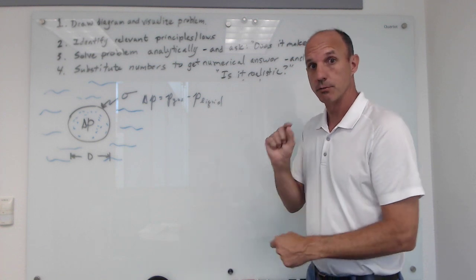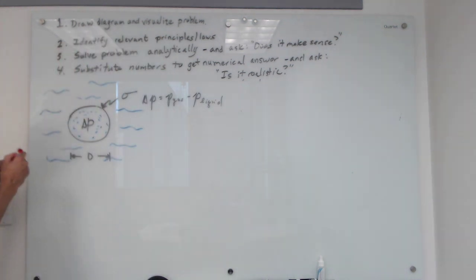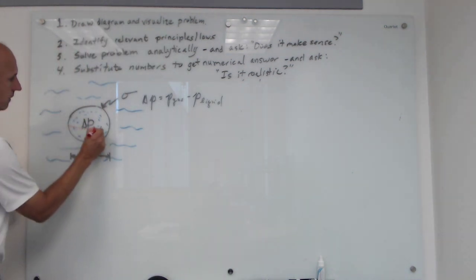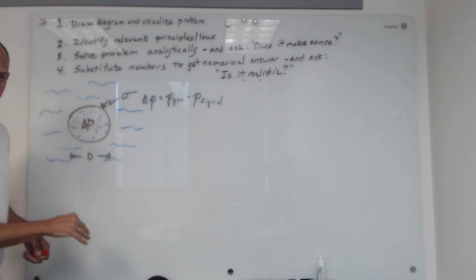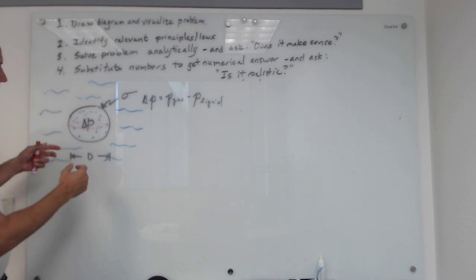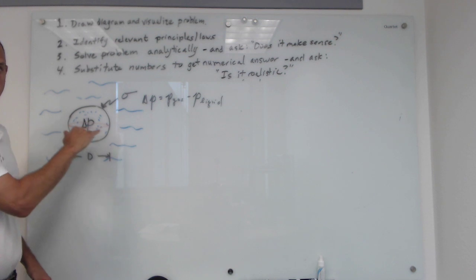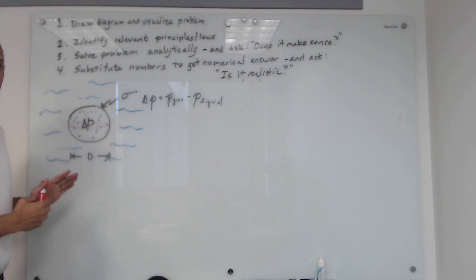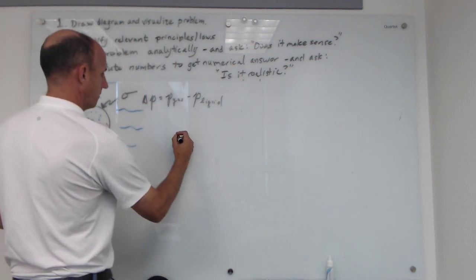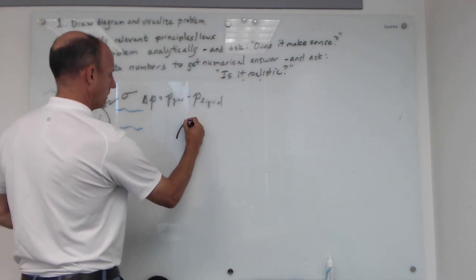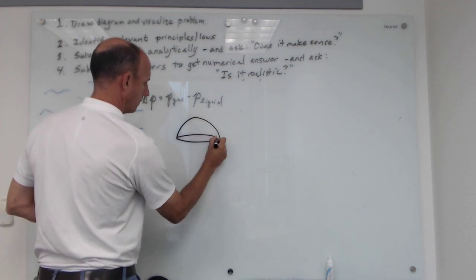But you don't, actually. There's a really clever way to think about the force balance, and that is to make a slice right through the center of the bubble, and to think about removing the bottom half of that bubble and doing a force balance in just the vertical direction. Because once you've sliced it horizontally right through the middle, all the forces are perfectly vertical. So with that in mind, we can draw a free body diagram of at least half the bubble.